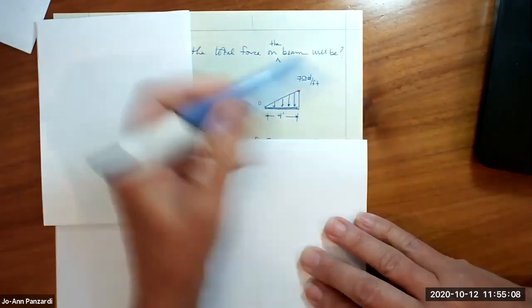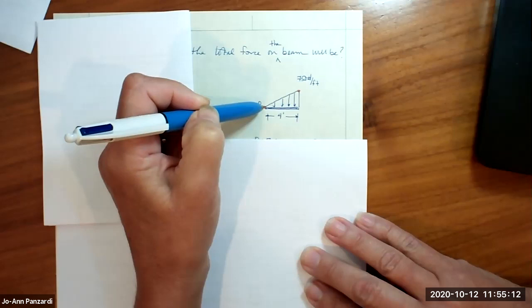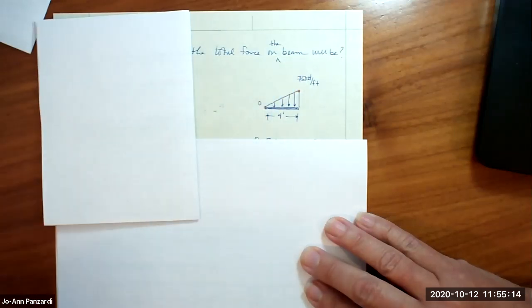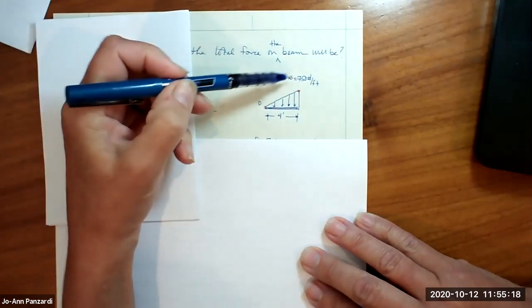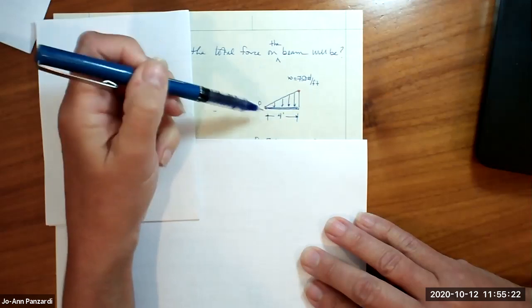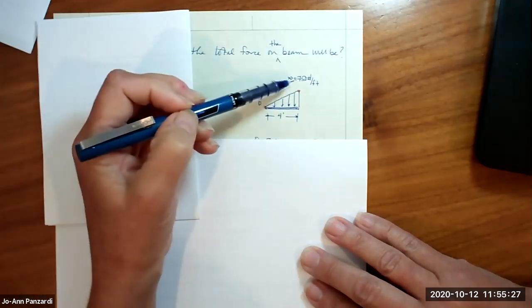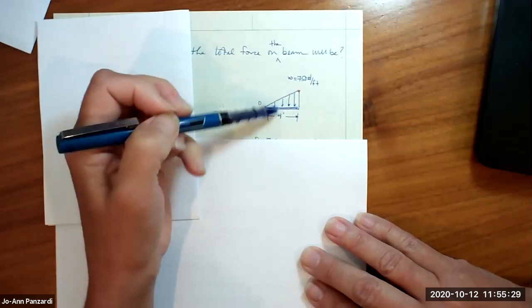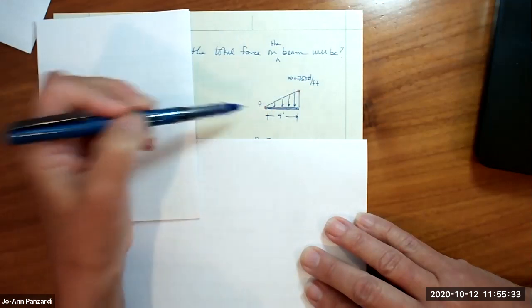So that means as we go along per foot, the amount of pounds per foot, and again, we could call this W, omega, this W, the pounds per foot along this length of this beam, is increasing linearly. Can you think about what kind of load is being created by the 700 pounds per foot at this end and 0 at that end?